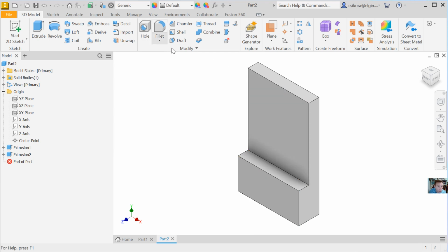Now there is the hole tool, which is really nice. It has countersinks, counterbores, all that fun stuff. But we just want a basic hole, and I'm still teaching you the basics on how to add and remove material. So with this hole, we'll actually do it the manual way, which is still pretty easy. Select this face, and again we'll go to Create Sketch.